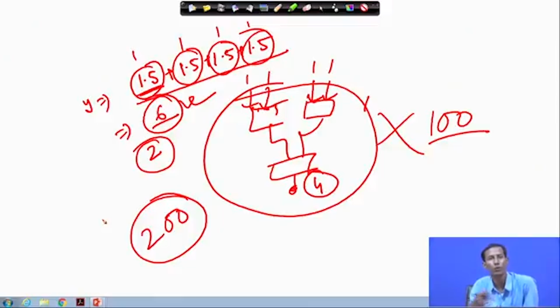Whenever we are doing the algorithmic verification, at that time if we consider only floating point number representation, we will not be that much bothered about this particular error accumulation. But as we are doing this fixed point operation in the hardware circuit, at that time we have to be more cautious about how much error I am accumulating whenever I am doing the corresponding operation, or that means this internal circuit of that hardware.